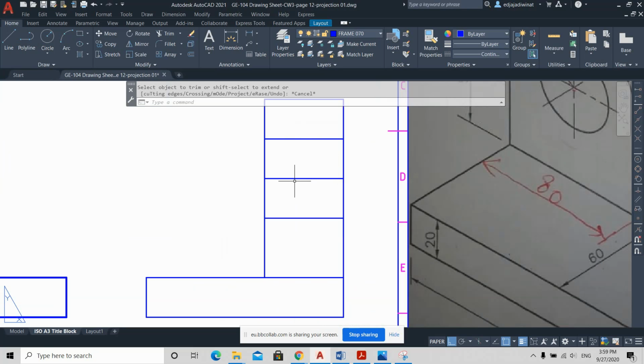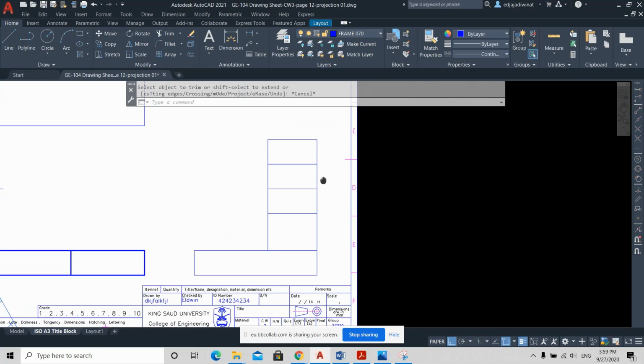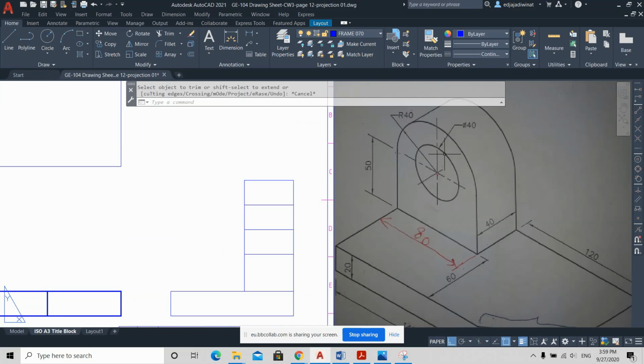Of course, you can offset from here to here. Another way, because the radius is 20, right? The radius is 20, so you can just offset. For example, I'll delete this. I will repeat. You can use offset because the radius is 20, so you will offset this edge to the center by 20. Once you're done, press enter. Is that clear until here? Everybody follows? Yes. Okay.